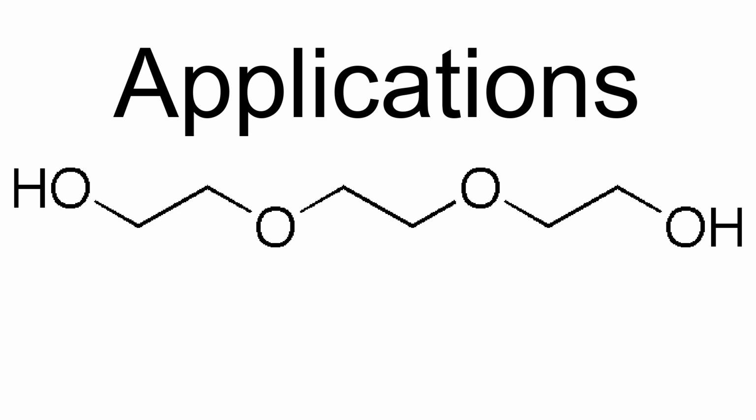It is necessary to dry natural gas to a certain point, as humidity in natural gas can cause pipelines to freeze and create other problems for end users of the natural gas. Triethylene glycol is placed into contact with natural gas and strips the water out of the gas. Triethylene glycol is heated to a high temperature and put through a condensing system, which removes the water as waste and reclaims the TEG for continuous reuse within the system.